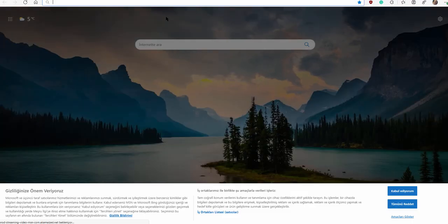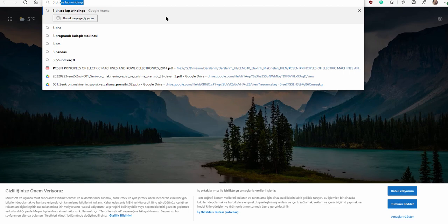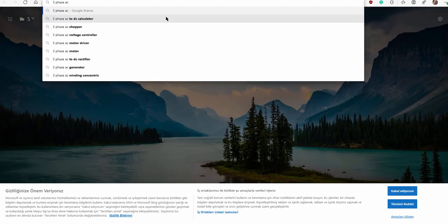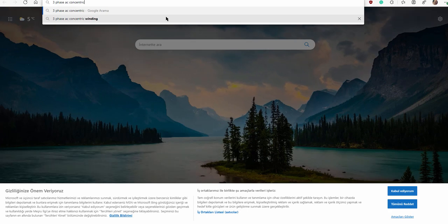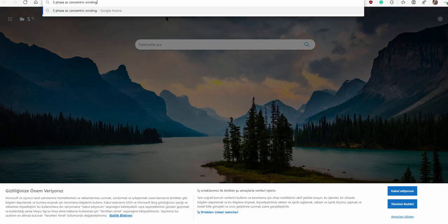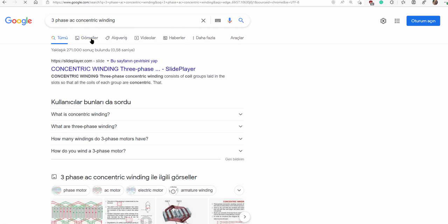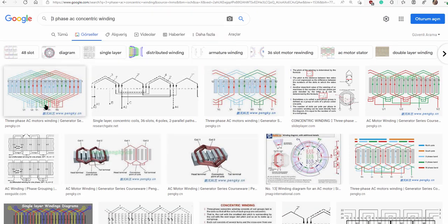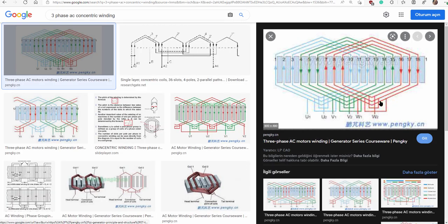And let me show you another 3-phase AC concentric winding. You see a concentric winding. For example, let's talk about blue one. Here blue coil has 3 subcoils. 1, 2, 3, 3 prime, 2 prime, 1 prime. Return of the 1 to 3.